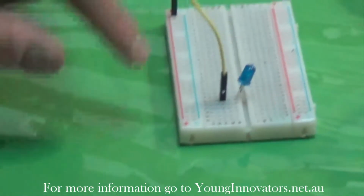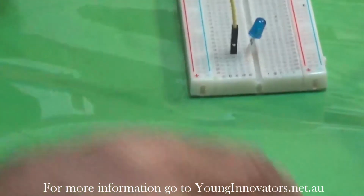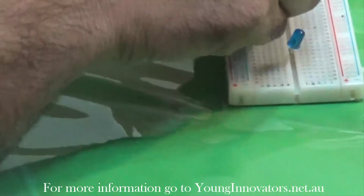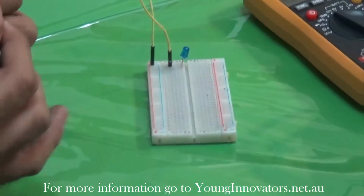And now the other end of the LED needs to go to a resistor, right? If I plug it to negative, it will blow away. So now we need a resistor, so we twist the resistor a little bit.